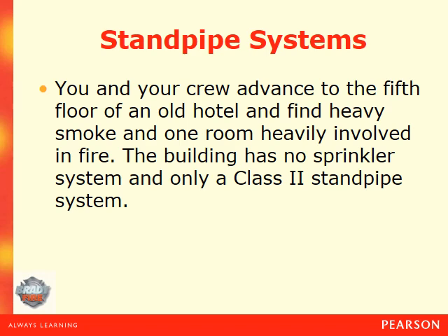Now, they don't recommend that firefighters use a Class 2 standpipe system. The reason being that the hose and nozzles are usually far less than what is required for adequate water flow to put out a room and contents fire. Also, there's no guarantee that the nozzle or the hose has been tested on an annual basis, which could lead to failure.